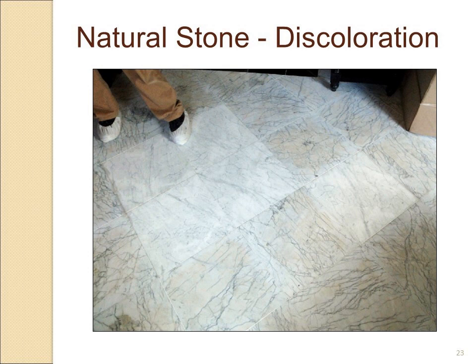So the story on this picture is we installed some new tiles into an old installation, and of course the thin set made the stone bleach out white. Well, we all know that's not what happened, but the amount of moisture that was in the slab affected the stone and therefore changed the color.